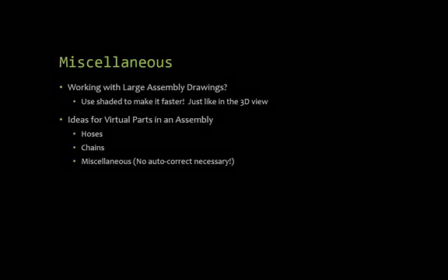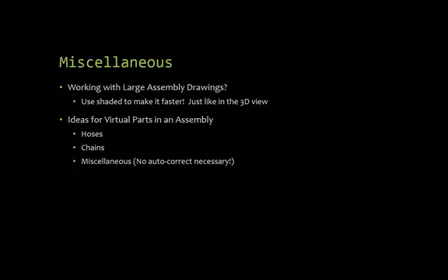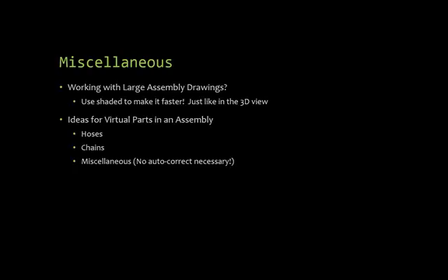Well, you have to remember, those views that we have in a drawing are just your 3D part captured in a particular orientation. So if you're working on a really large drawing and you're noticing really big hits to your computer, go to it, take the view, turn it into shaded with edges even, and you're going to find there's a huge increase in your speed.